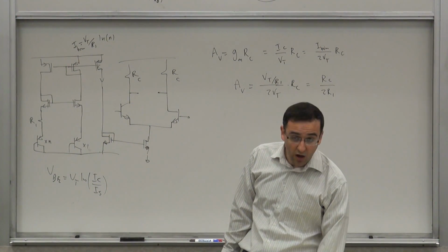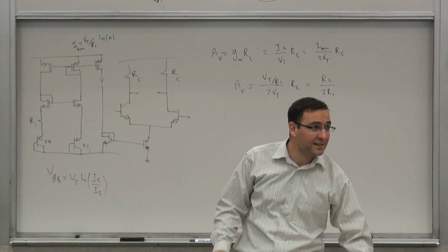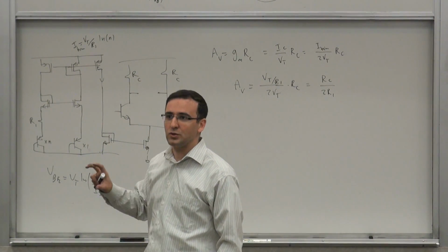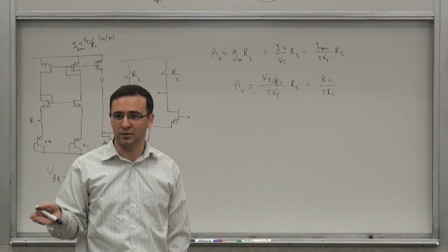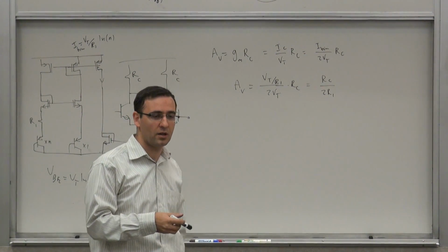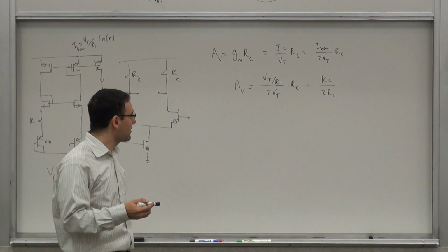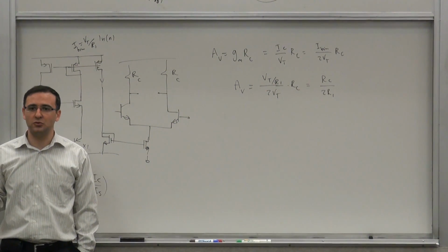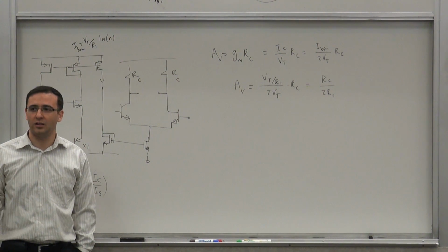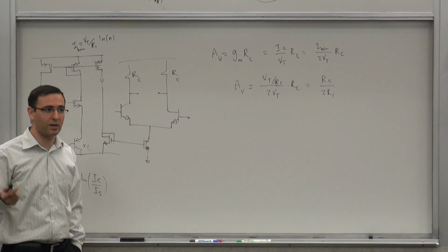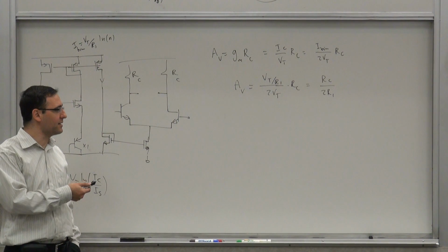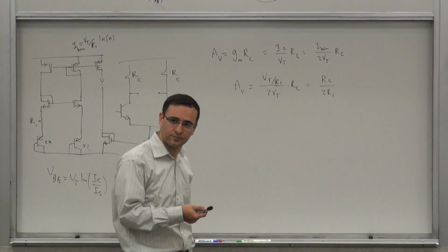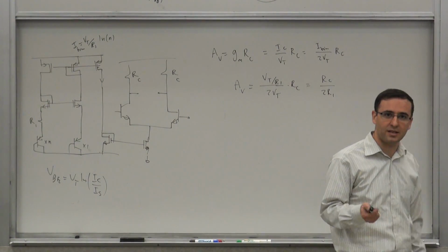So what we saw today, we basically learned how to make that little reference current, right? And we see that depending on what you're using it for, you may use a different one. But there are different kinds that we can use, and to use it as a reference. We saw that you never eliminate anything, you just reduce the dependence on different parameters, but you can reduce it quite a bit. And these are very useful techniques in biasing things independent of supply and temperature. Alright, if there are no questions, let's take a quick break.